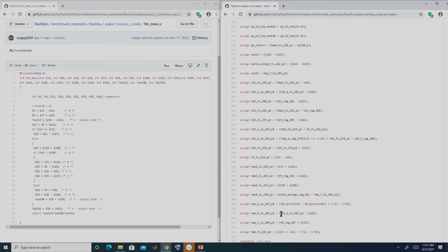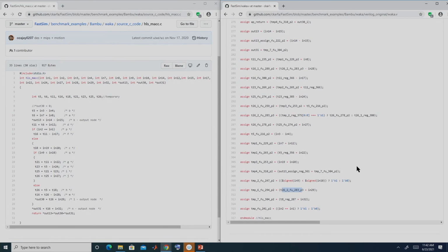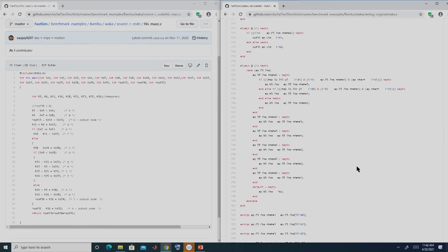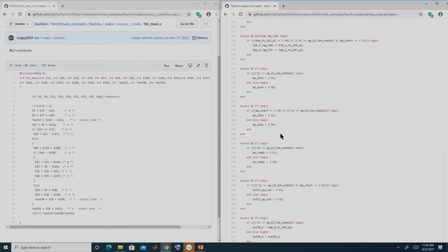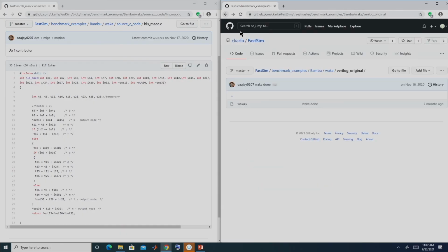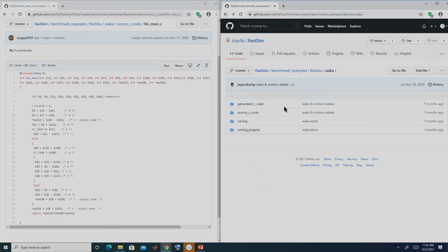Then I have to take this and find the operation which will replace this, right. This way the rewriting operation is happening. So, this is the RTL, which is actually generated, where these assign statements are the OR assignments which are always true, and these are the register transfer operations initiated state-wise, right. So, from this behavior we are able to generate a C code, right.